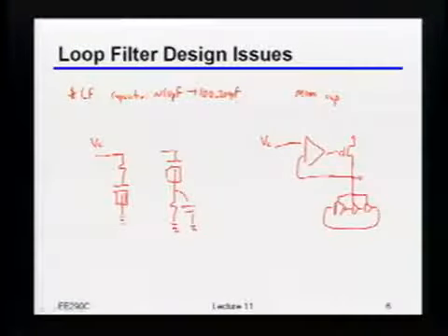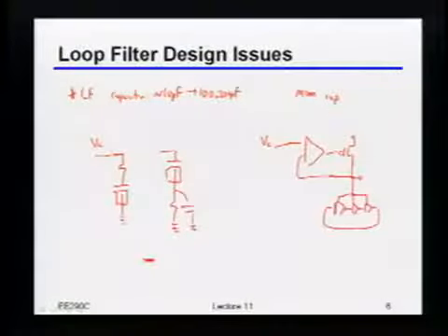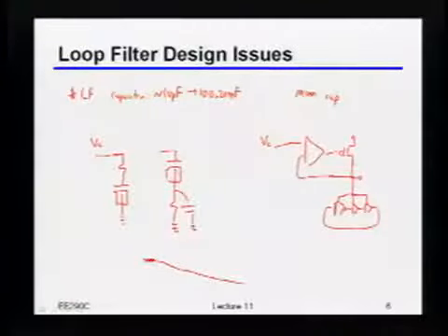So what would that do in this context? What would happen to us if we actually tried to use a MOS cap with that MOS cap having gate leakage in it? What would that do to the PLL? Is that fine? Or what's that going to do? Frequency would drift. Yeah, basically, if you looked at the control voltage, let's say you nominally wanted to start somewhere, but you've got that leakage on there, right? So it just starts drooping down, okay?